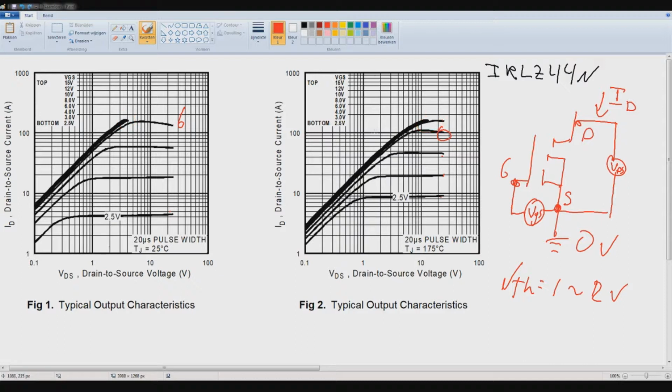And you see there's a little bit of gained VDS voltage, but what we can see is that it went a little from here to over here, meaning that the VDS voltage had to be increased. So the voltage at this point had to be increased to get about the same current, which is the reason it comes from the resistance increasing.